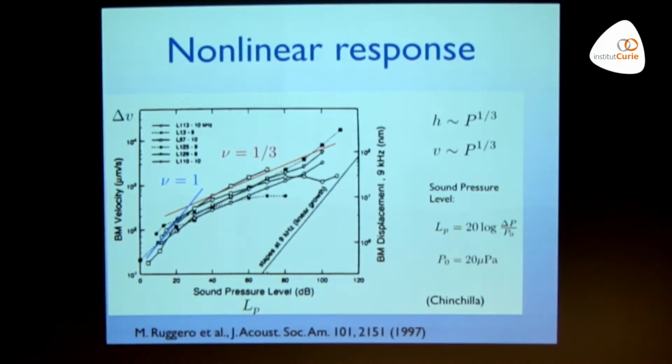While if one does the same experiment choosing a different frequency, or with the same frequency at a different position, one would see a linear response over the whole range, which means this blue slope. Typically, for strong amplitudes you get the same response as in the linear case, and the linear response then corresponds essentially to this line here, which means for weak inputs, you get much less vibration amplitude in response than at this critical resonant condition.